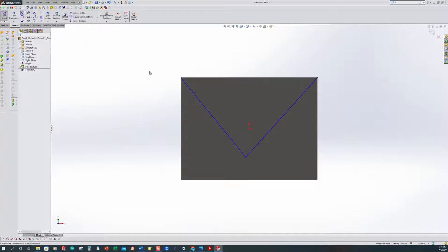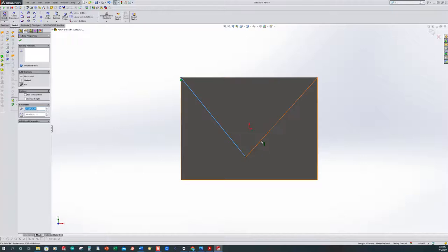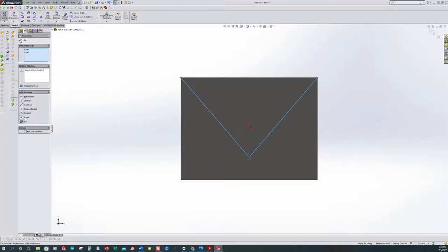Now use your escape key a couple times. So there's a black line up here. It's hard to see with this object back behind it, but it is. I intentionally drew mine skewed so I can show you how these things need to be related. So if you'll hold your control key down, hold Control and one mouse click and a second mouse click, that automatically puts us into adding relations, and I want to make both of these lines equal. Alright, so I accept it.